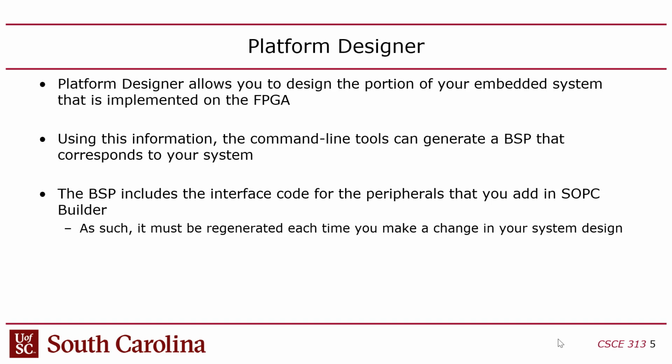Now, the BSP is customized for the hardware, though. So every time you regenerate your hardware, you have to regenerate the BSP. The BSP is like a software layer that has to be generated specifically for your hardware setup. Does that make sense? Okay, I told you it's going to get a little complicated, but once you start working with it, it'll make sense.